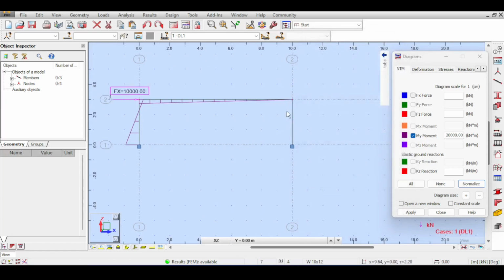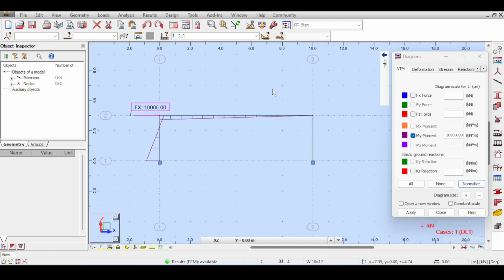Now, you might be interested in seeing how this 10,000 force actually causes the partial or the full collapse of the structure. And this is really interesting, and this leads me to the second part of this video, which is going to be the pushover analysis. You see, the pushover analysis was created to push the structure up to a certain displacement and see where the structure might fail, to identify the weak points of the structure and make sure that there is no progressive collapse in the structure. Basically, that the collapse of that point should not put the entire structure in jeopardy.